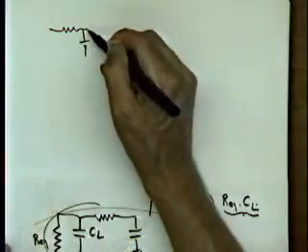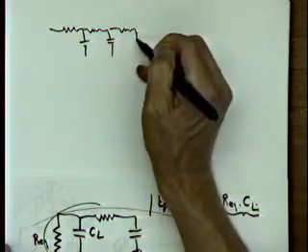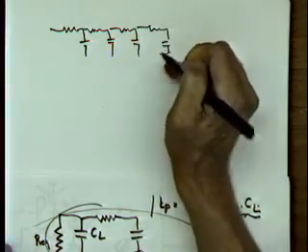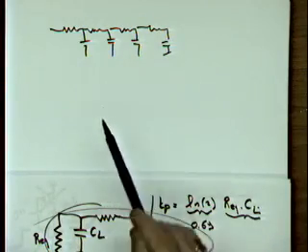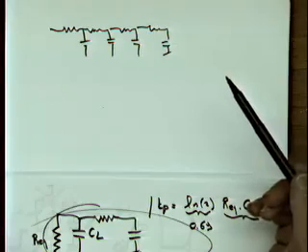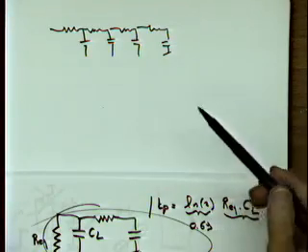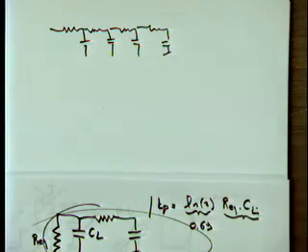However, there's some beauty to it. We'll show later, when we talk about wires, which we typically model as networks like this, with resistors and capacitors in series, that there's a fairly simple way for me to estimate the first order moment, as they call it, which is very close to what we call the dominant time constant of this network. That can help me predict the propagation delay without having to go to this very complex differential equation story.